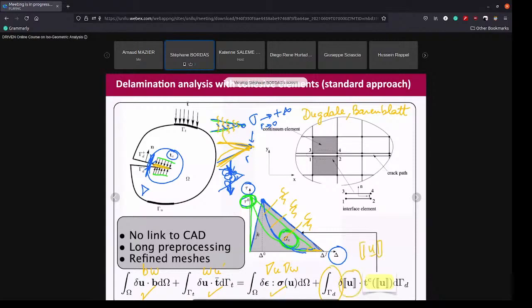You have to linearize it, because this is a nonlinear function, obviously, because, well, maybe it's not obvious actually, but this U is an unknown, because the solution enters in the calculation of the jump. You need the solution to compute the jump. So you have that type of non-linearity when a function in the problem depends on the solution itself, right? So this is a function of U, and U is unknown. So therefore, this is a nonlinear case. You can linearize that using a consistent linearization that you do in plasticity as well. It's very similar. So it's basically variational inequalities as well, similar to contact.